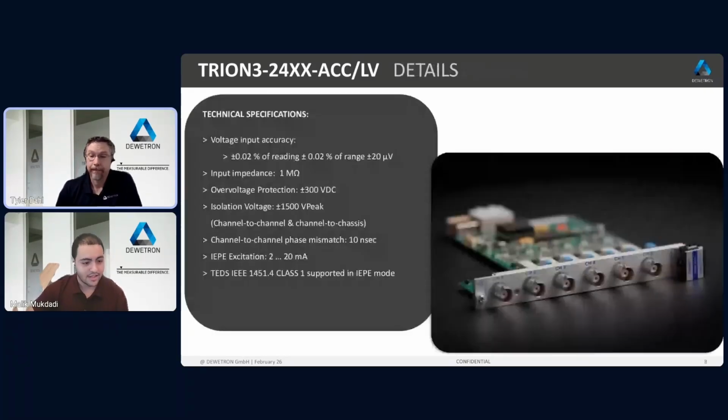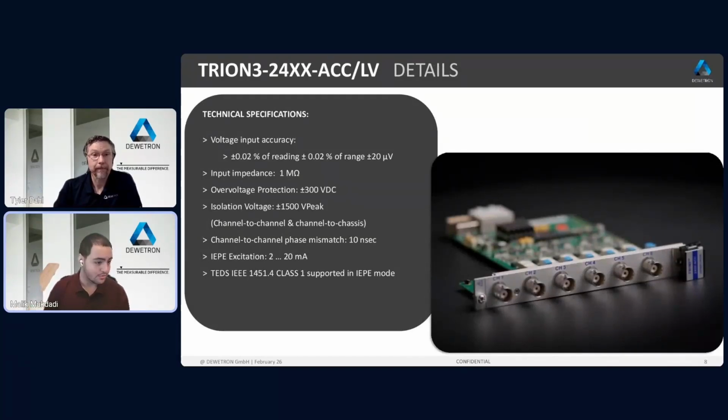Yeah, and to add on to that, we've also improved the specifications of the board as well. So I won't dive into every single specification that we've improved on. You'll be able to reference that in our technical manual that you can find in our customer care center. However, some key features that I really want to point out is the accuracy. The voltage input accuracy is up to plus minus 0.02% of the reading, plus minus 0.02% of the range, coming in with 20 microvolts of noise. So the total error is very, very low.